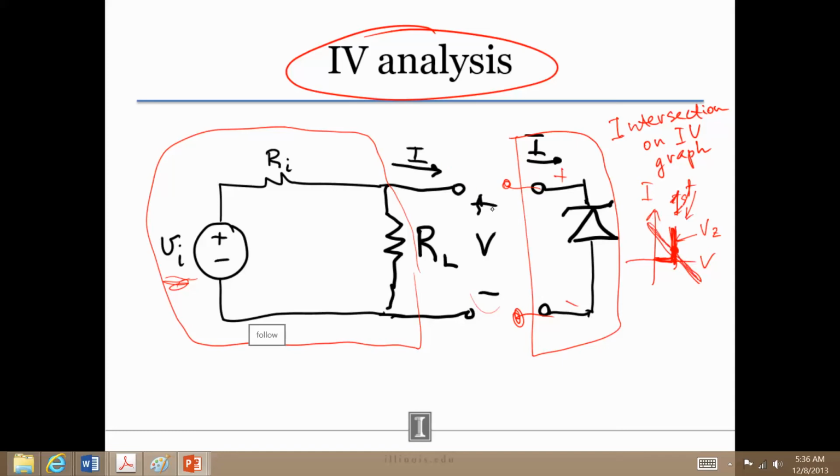And if we look at all the possible lines like this, the diagonal lines that represent the source on the left, some of them will intersect the vertical part of the Zener diode curve, like this one. But some of them at some point can intersect this horizontal part of the curve, which represents the Zener diode that's in the off state. All right, so what is the slope of this line going to be guided by? Well, it's going to be guided by some sort of resistance relationships, right? So R_L and R_I. So we'll see at which point the curve intersects on the off part, and at which point the curve intersects in the breakdown part. And let's give ourselves a little bit of room.